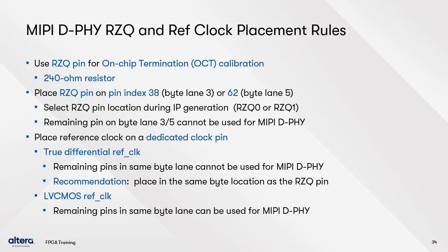For DPHY PLL reference clocks, you must assign the MIPI reference clock to a dedicated clock pin on the FPGA. If your reference clock uses the true differential I/O standard, then that byte location chosen can no longer be used for the MIPI DPHY functions.